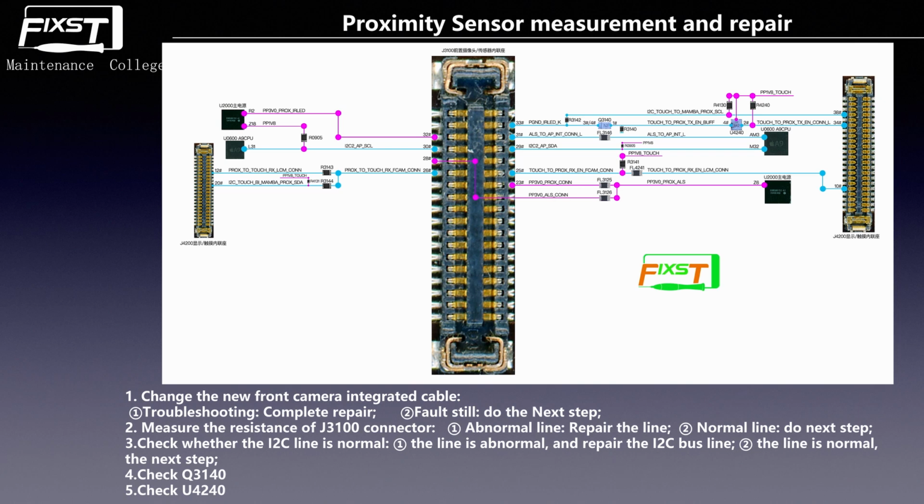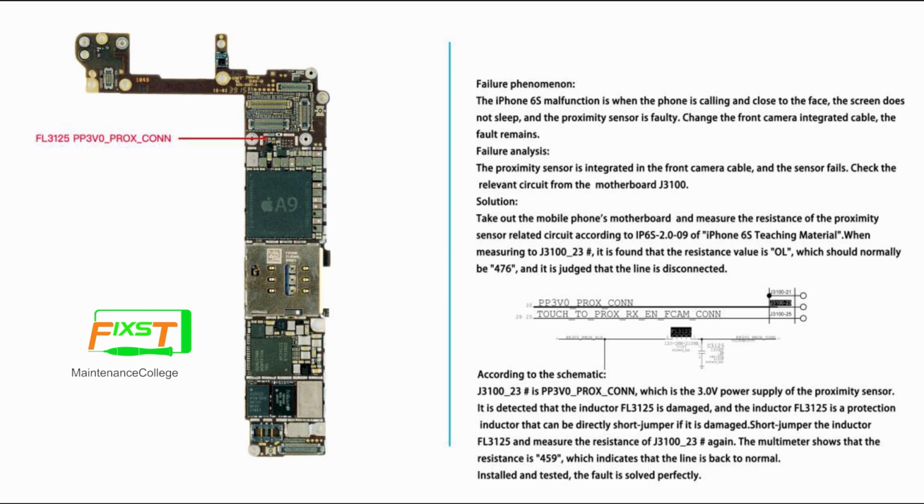Why does it have CAT1, CAT2? Because I told you before, it has 2 groups of LEDs, so it needs 2 loop circuits. So you just need to know that for the backlight to work normally, it needs the IC. Okay, now we show you a case to let you understand it easily.